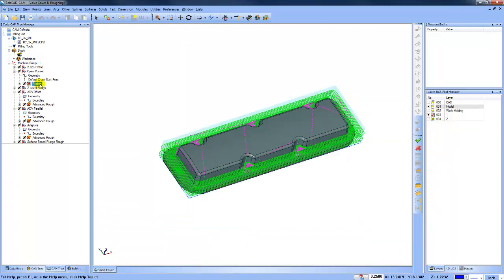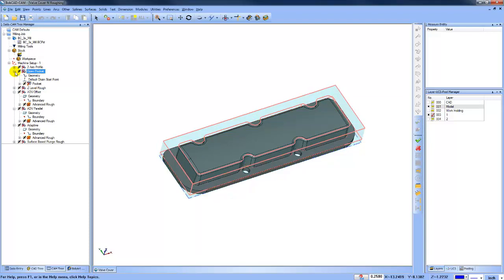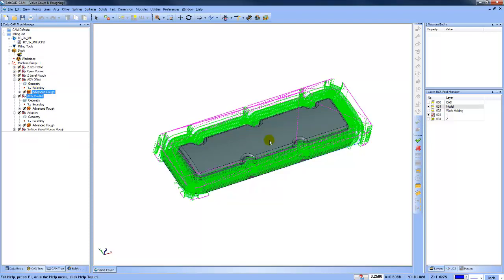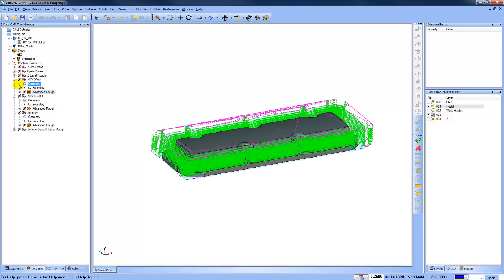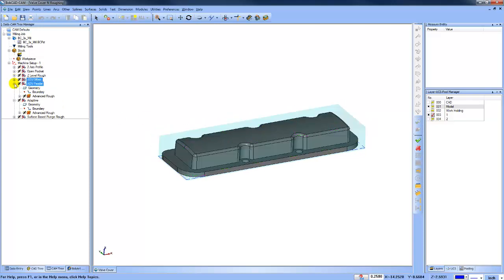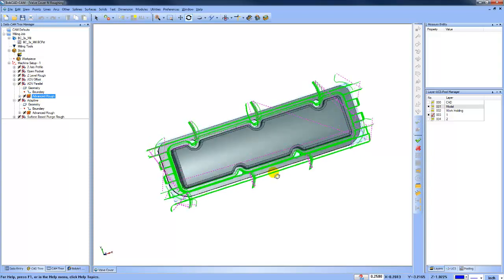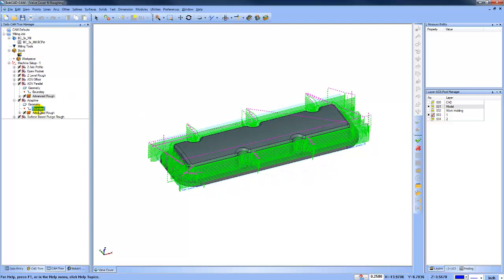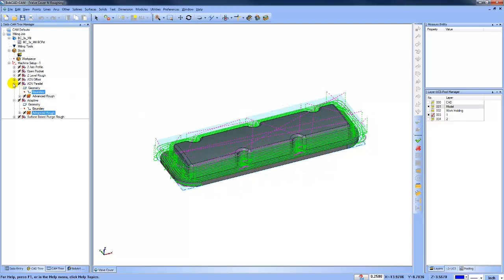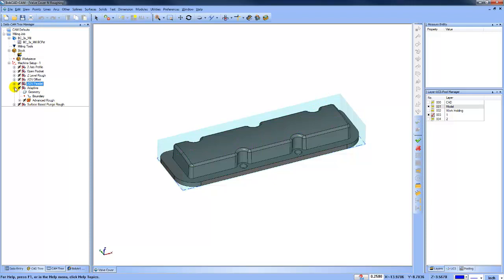As far as the toolpath pattern, what's different is one is a 2D toolpath, which wouldn't accommodate for the tapered walls or any curved surfaces, and the other one is a 3D toolpath, which would accomplish that. You can cut in single direction or bidirectional. You can force the tool to start from the outside of the part so that it doesn't plunge in on any of the material, and that's what you're seeing in this parallel routine. So again, advanced roughing is probably going to be your go-to if you're a Mill Professional user.